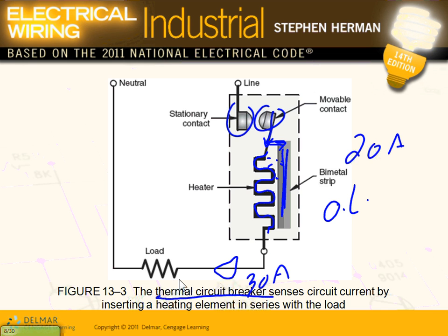So that's mainly an air type circuit breaker. We're talking about air here. Everything that we're going to talk about right now is air. Would these circuit breakers generally be for motors? You can use it for feeders, for any application. This technology, Chris, is not only for motors. Motors, guys, because they're so special, we have this circuit breaker to protect from overload and a separate device that also looks at the overload.